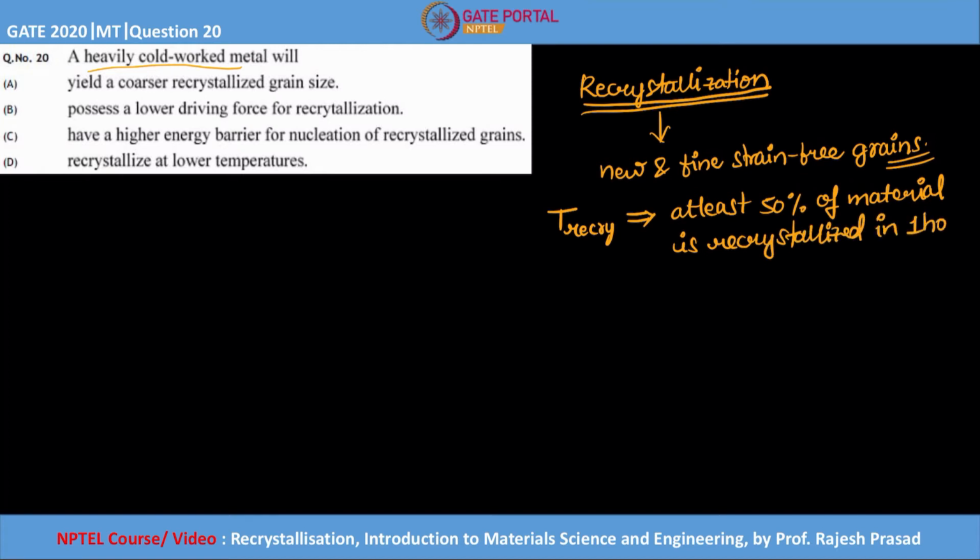So the time is also important here. In 1 hour, at what temperature is at least half of my material recrystallizing? That is my temperature of recrystallization.